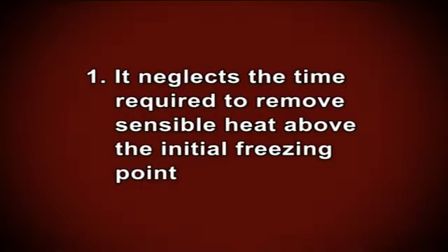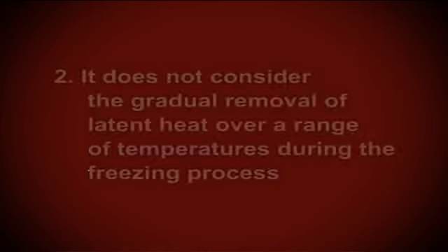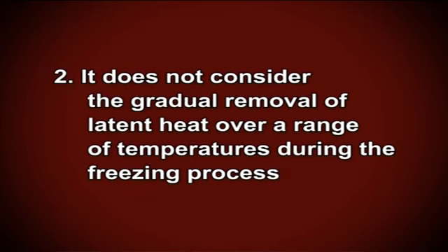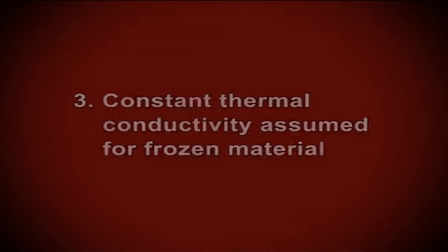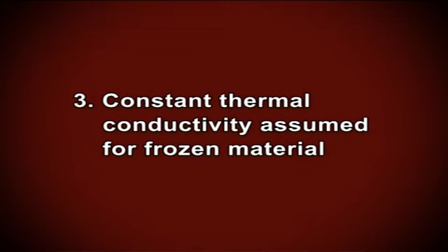1. It neglects the time required to remove sensible heat above the initial freezing point. 2. It does not consider the gradual removal of latent heat over a range of temperatures during the freezing process. 3. Constant thermal conductivity is assumed for the frozen material. Despite these limitations, Planck's equation is the most popular method for predicting freezing time.